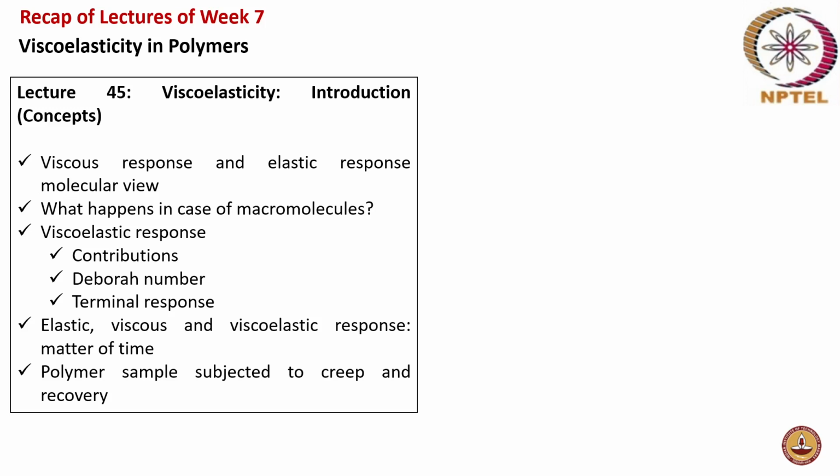In both pure elastic and pure viscous response, the history is not considered. The elastic response is more of a storage response, and the current state of stress and current state of strain are considered, whereas the viscous response is a dissipative response, and the current state of stress and the current state of strain rate are considered.